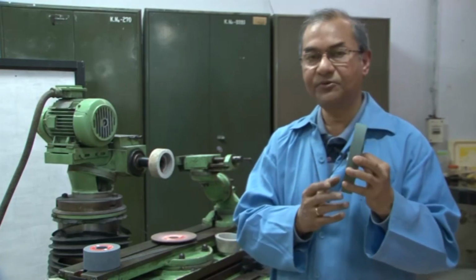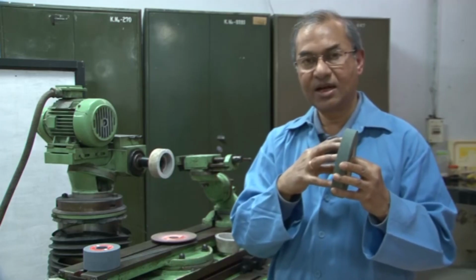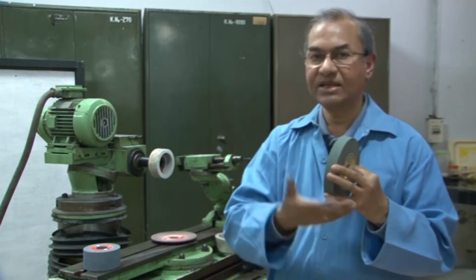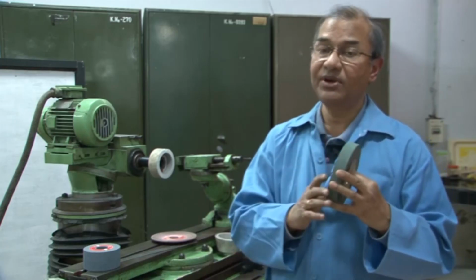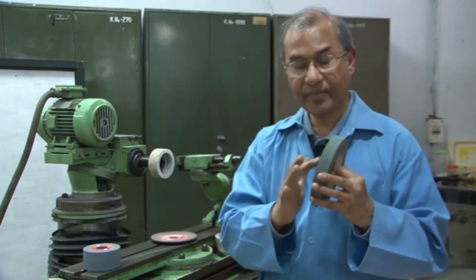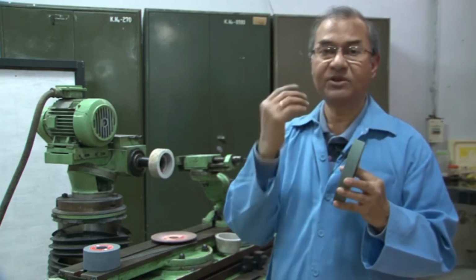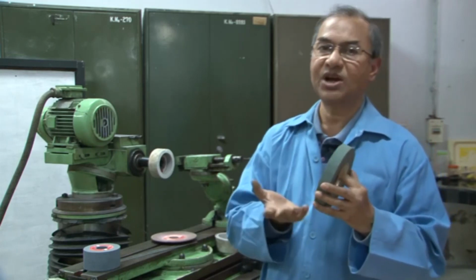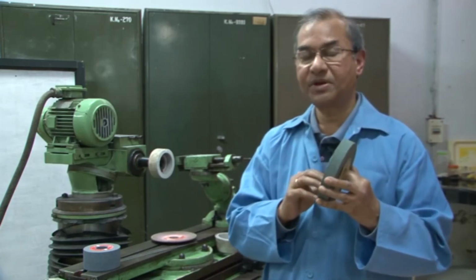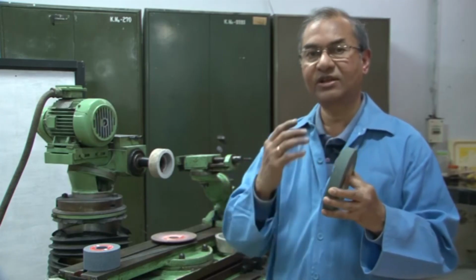Okay. That means, if you have a very hard material and you are using the silicate bond in the grinding wheel, then the worn out grains will be easily dislodged. Those grinding wheels are used for grinding a small space in the tool, because only the tool tip has to be ground, for example, resharpened. In that case, you do not want a very high temperature to be produced, so that the vicinity of the tip is not thermally deformed.